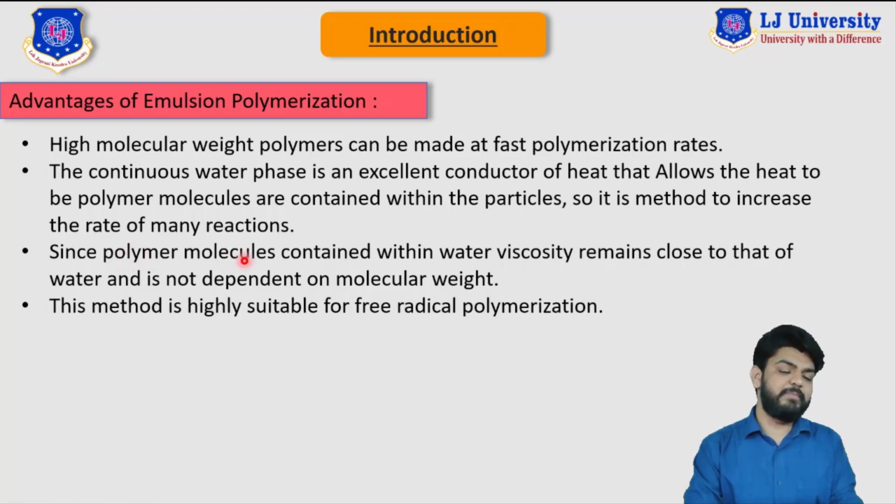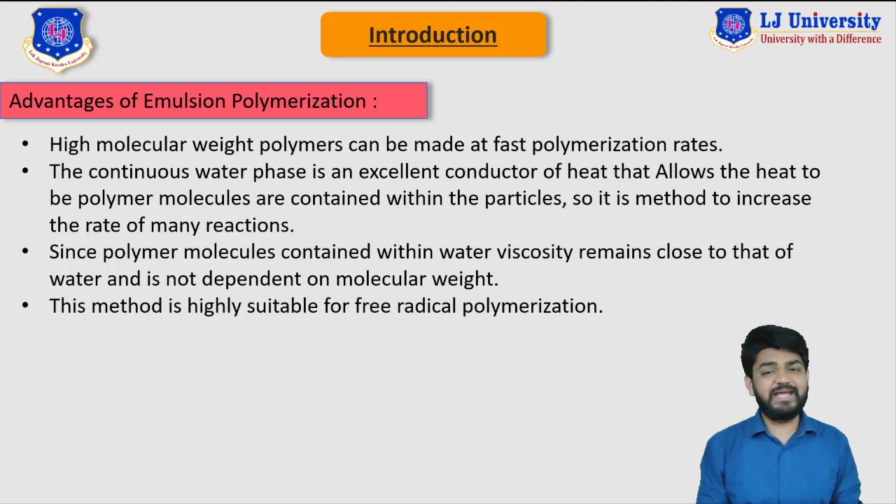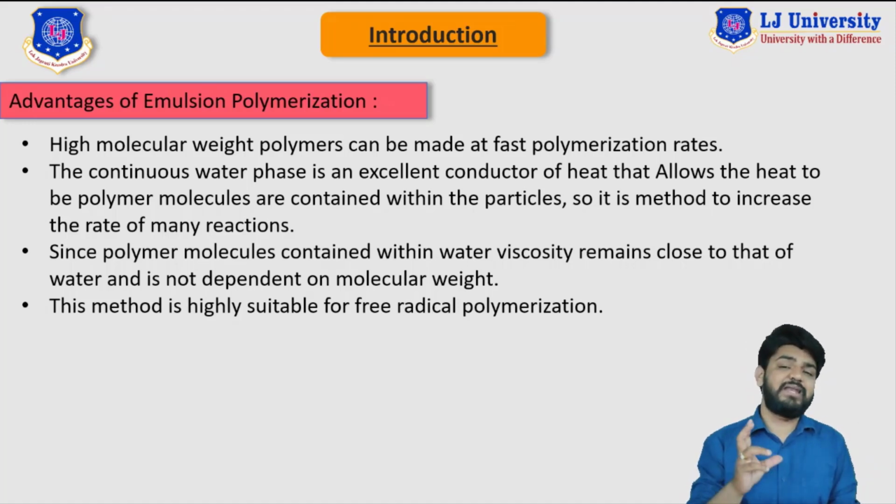Now, since the polymer molecules are contained within the water, viscosity remains close to that of water and is not dependent on the molecular weight. So the entire reaction mixture has a lower viscosity, similar to water, and water is not that viscous. So we can easily agitate, and we can easily achieve mass transfer at a higher rate with this type of technique.